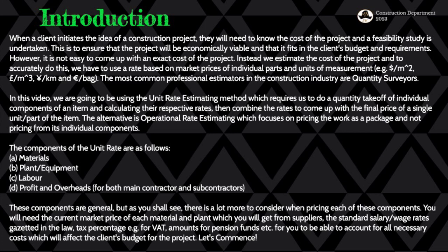So when you do your quantity takeoff for the quantities that you're dealing with, you have many dimensions. Either you'll be dealing with square meters, so you need length and width. If you're dealing with cubic, you need length, width, and height, or depth. If you're dealing with a circular plan, maybe you need pi r squared. Depending on what you are dealing with, you need the radius, and then you square it, and then you multiply with the pi, or say 22/7, or 3.142 by that radius squared.